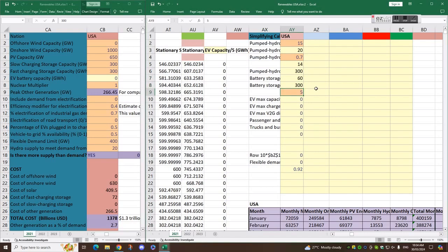To work out the peak power, it's simply the energy, 300 gigawatt hours, divided by the minimum duration, 5 hours. So 300 divided by 5 equals 60. For the pumped hydro, 300 divided by 15 equals 20 gigawatts of maximum power. I'll change this back to 3 hour duration.